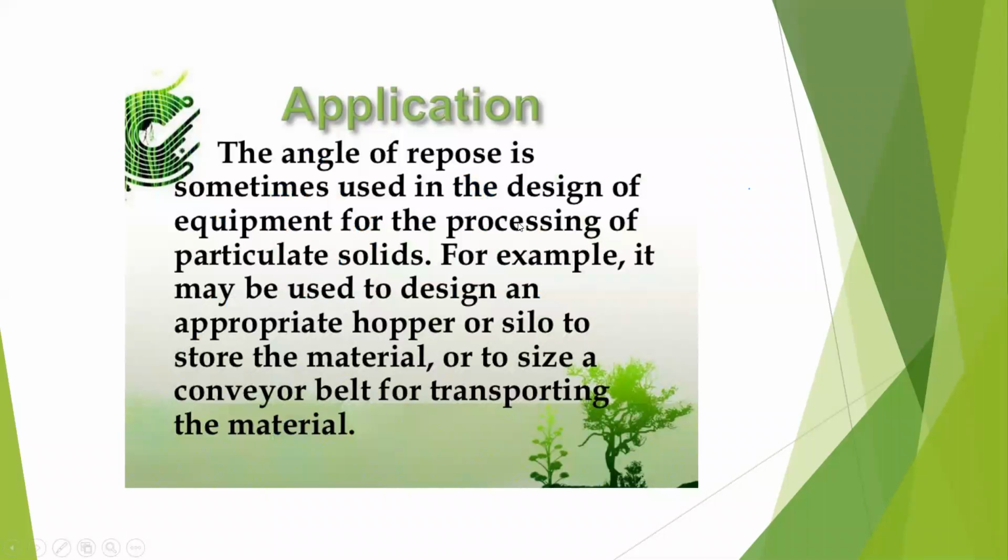So what is the application of this angle of repose? See here, students. The angle of repose is sometimes used in the design of equipment for the processing of particulate solids. For example, it may be used to design an appropriate hopper or a silo to store the material, or to size a conveyor belt for transporting the material. So in all these processes, we are using the help of angle of repose. So if you understand the angle of repose concept, then all these phenomena will be easy.